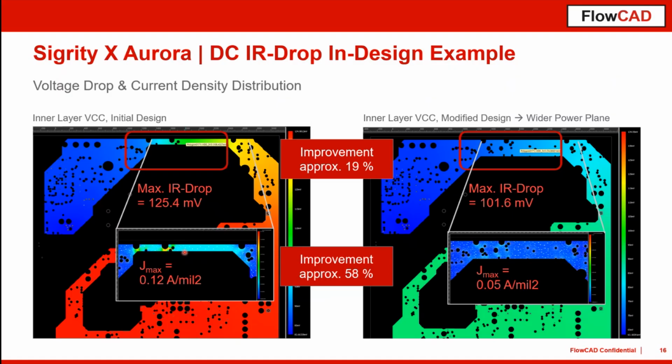So once you fix these problems directly here in your design, enlarge the shapes, and then rerun the simulation. The simulation for this IR drop analysis takes less than half a minute, and then you can see, oh, I already achieved a very good result just by enlarging the shape a little bit wider, and we can see that was a good idea.